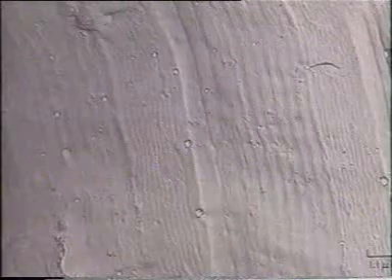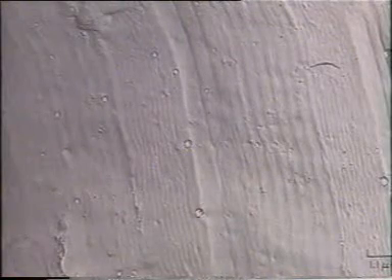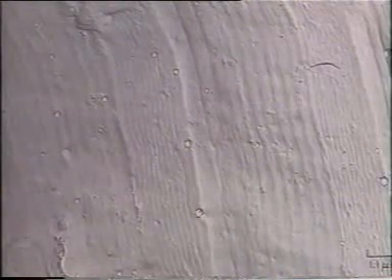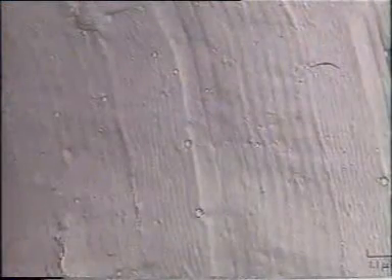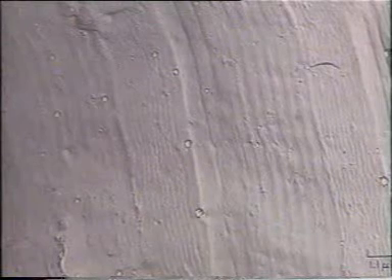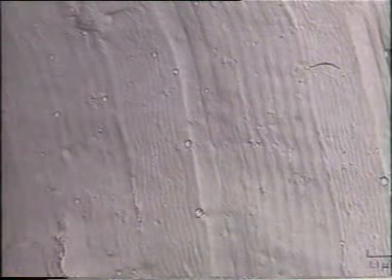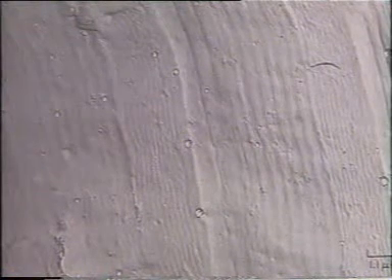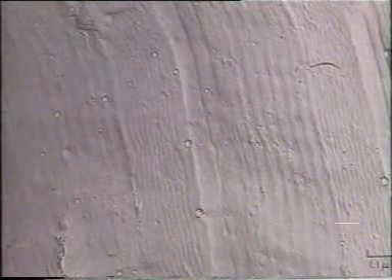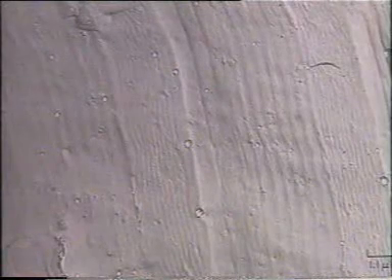These striations are characteristic of fatigue fracture in many metals. However, the striations are not always present, especially when the metal has little ductility. They are also easily damaged by corrosion, mechanical action, or post-fracture damage. Two sets of striations can be seen. The widely spaced striations are caused by a higher stress. The more closely spaced are lower stress.